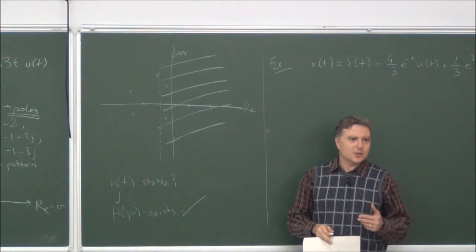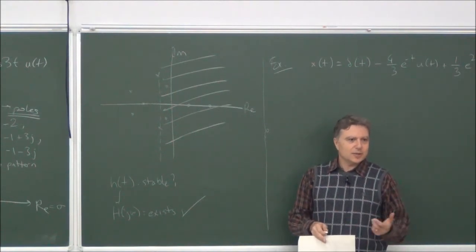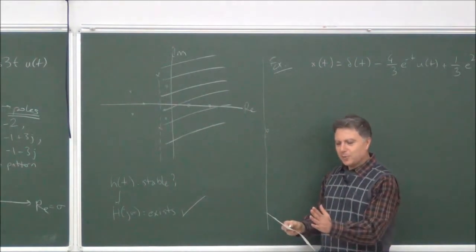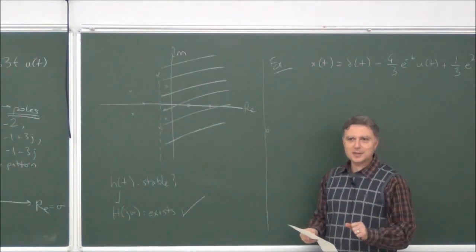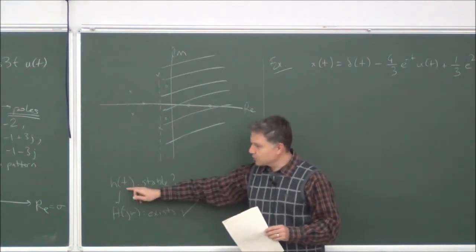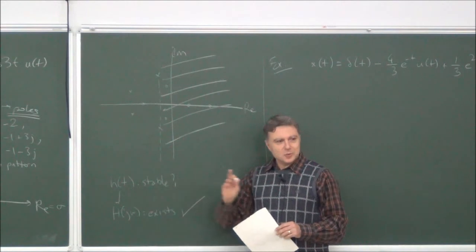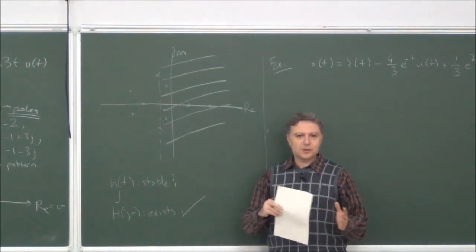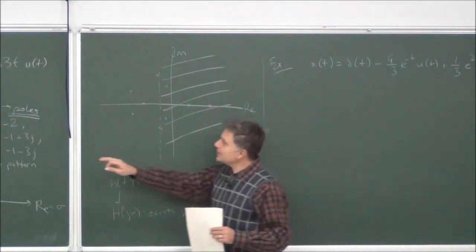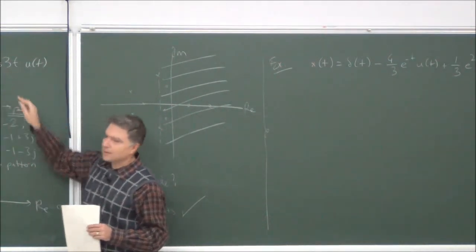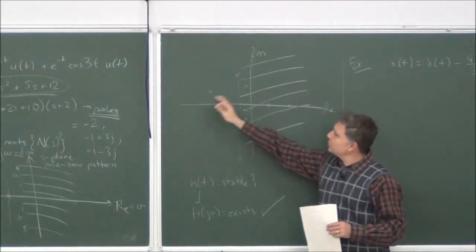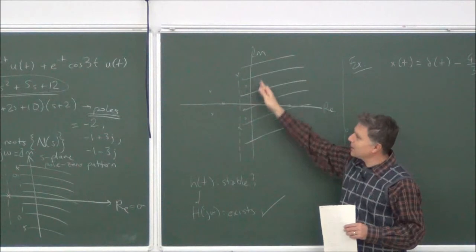And in the control system society, that's what they usually take a look at. They look at the poles and the zeros. If all of the poles are at the left-hand plane, that's a good thing. It means it's a stable system in terms of h of t, of course. But there is one condition that most of the control people just forget about, because they assume it naturally. It is the right-hand-sidedness of the impulse response. Only if the impulse response is right-hand-sided, then the poles should be at the left-hand plane, so that this j omega axis is included.